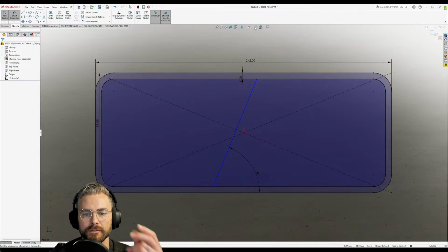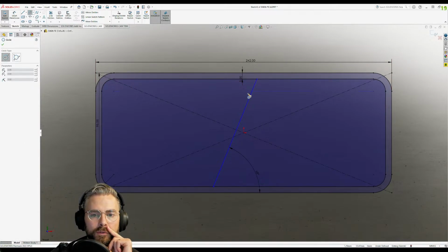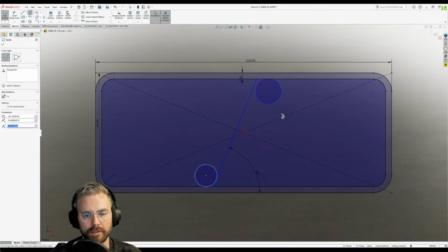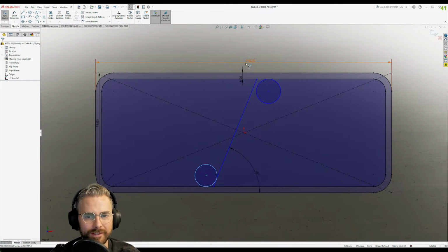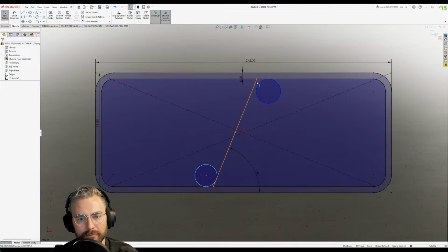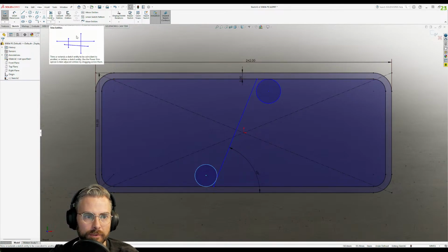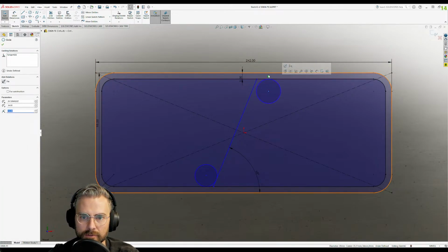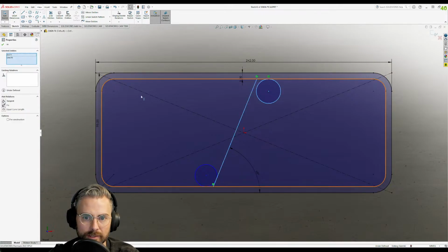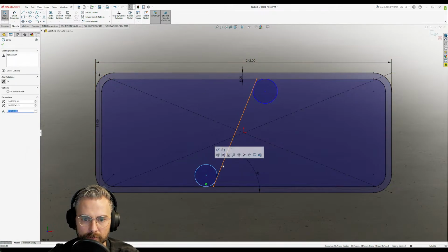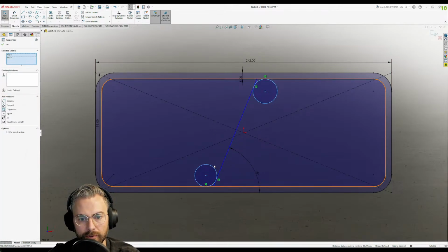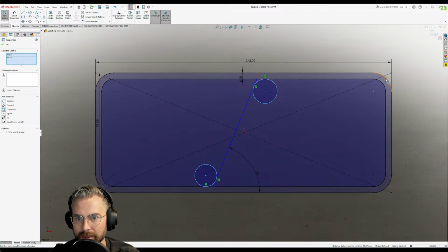And we are going to go ahead and do a radius here, because there is a radius. This is another way of doing a radius. I could do a fillet here, but I don't want to because it's going to break some relations. So I'm putting a circle here, and I'm going to use the trim command to trim some lines. But first, I've got this as already tangent to that line. I want it tangent to this line. And we're going to take this one and make it tangent also to this line. And since these are all the same size as this, oh shoot, no.